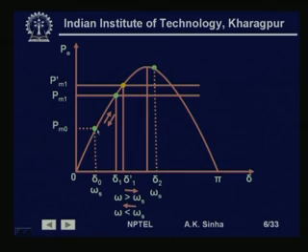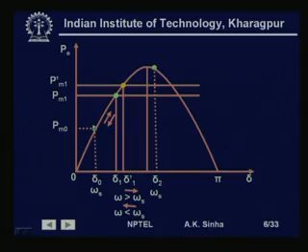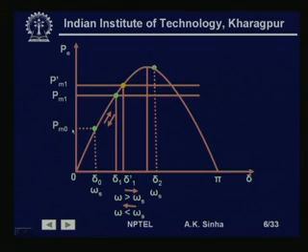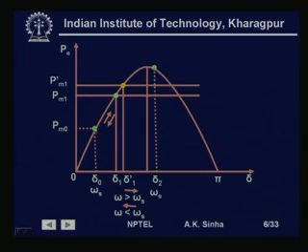So, this is the initial operating point, the steady state point, and the system is working at synchronous speed at this point, that is, mechanical input Pm0 and electrical output Pe equal to Pm0 and the power angle of the machine as delta 0. The speed of the system is synchronous speed because Pm and Pe are equal. So, it is a stable operating point where the system is working, or this is the steady state operating point where the system is working.